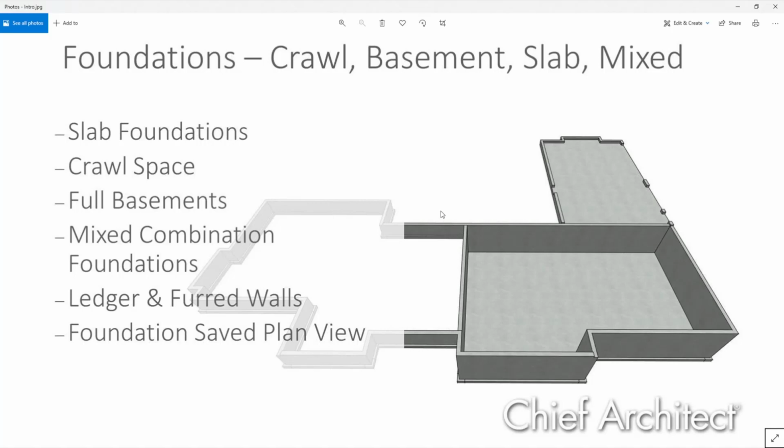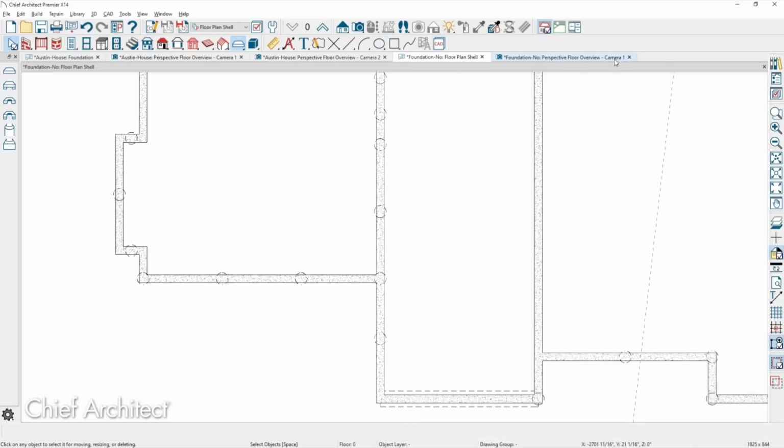So let's make sure we understand your question here. You're using a stem wall to build your slabs, and in some places you need a load-bearing wall to have an additional slab footing underneath it. Is that right? Correct. It's like the monolithic slab beams. It's the way it's drawn. It's got a 45 on the bottom. It's only a thickened 8-inch slab.